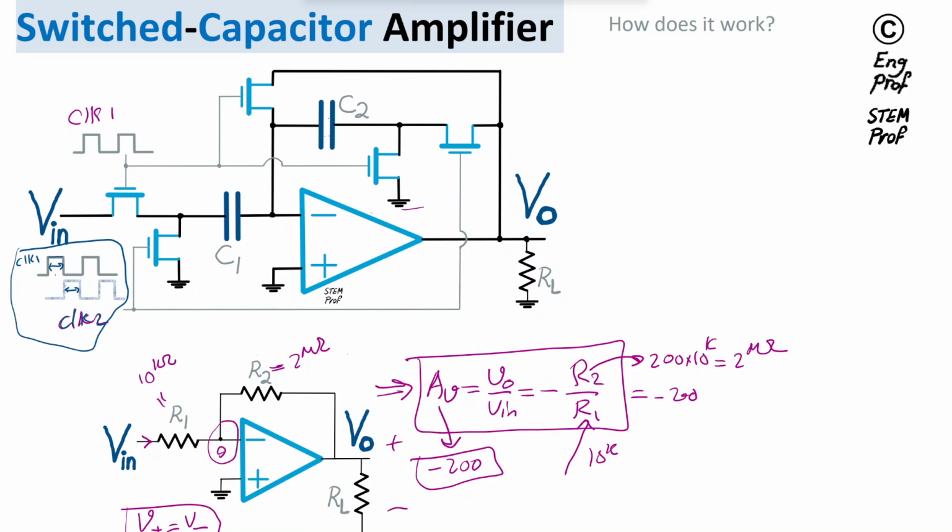At the same time, there is a preference that practically there should be a gap between the falling edge of clock 1 and the rising edge of clock 2, and vice versa. Between the falling edge of clock 2 and the rising edge of clock 1, there are dead zones, so that we make sure there is no time, even in practical implementation when clocks might suffer from some shift or offset, when all the transistors are temporarily on at the same time. So practically speaking, we would like to have a gap between them. Okay, so that's the relationship between clock 1 and clock 2.